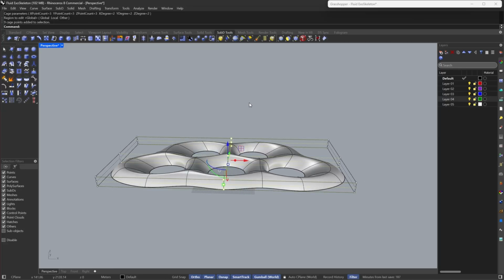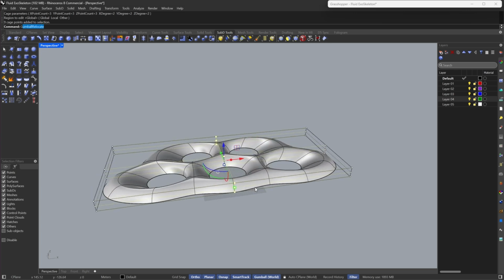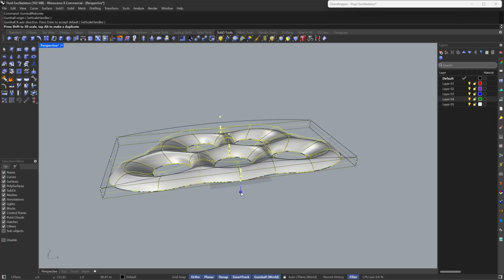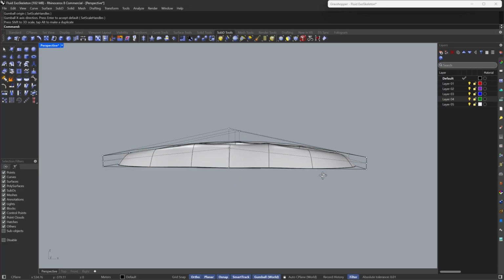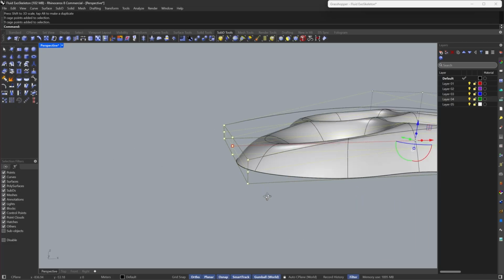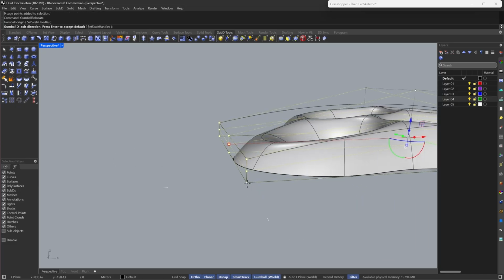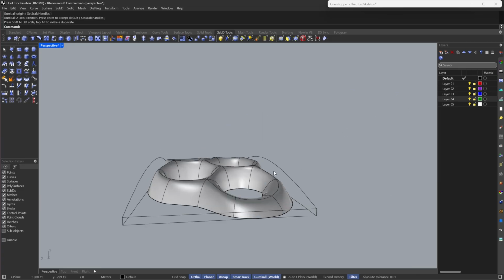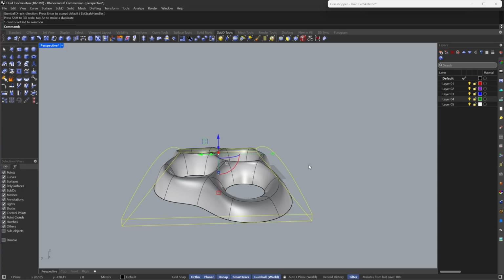And right now I'm going to select all of these middle points and Gumball relocate, and select the lower point in here, and probably stretch it a little bit, so this will make the whole shape go up like that. And maybe try to Gumball relocate again on this side and do something like this, so the whole shape will look like that, maybe.